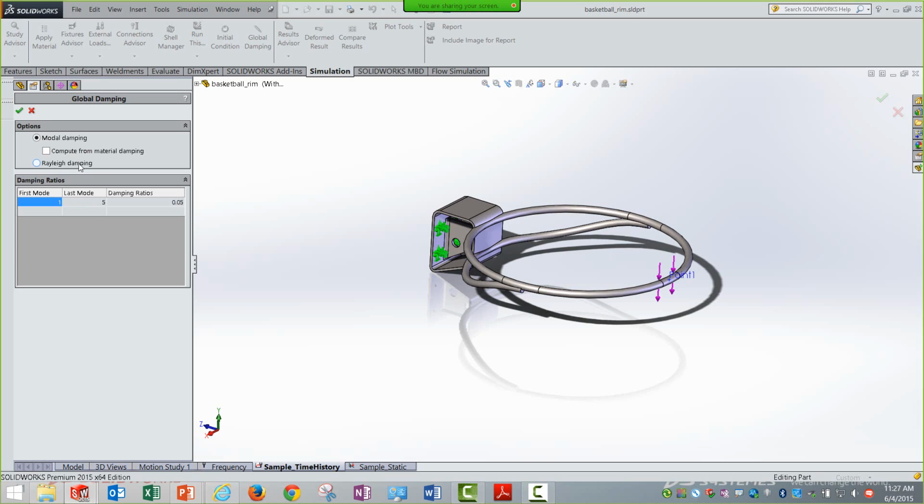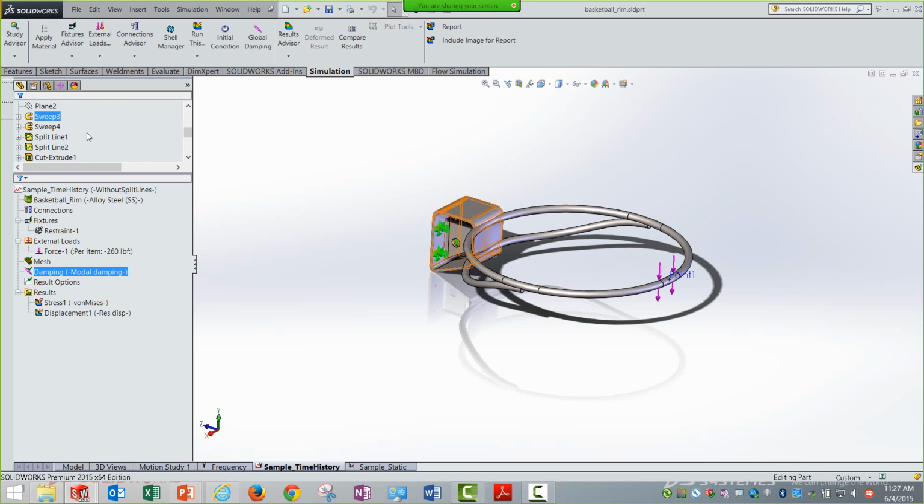Talking about damping, typically it is a bit difficult to know these damping values. It is a different domain itself. If I take this particular example, we are using something called modal damping, and we are giving a ratio of 0.05. So it is enough damping to dampen the system, but this may not be your true case as well. It is difficult to find the damping values, so you can use the standard or generic values, but this is what it is all about.